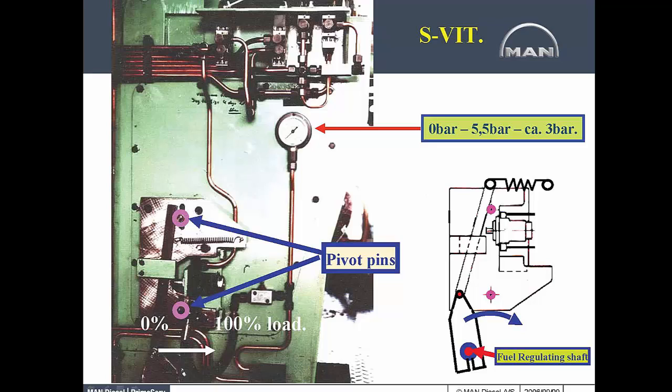And then you have 2 pins, these pivot pins. So if you look to your right, as that governor moves forward, that bar is going to pivot off the upper pin, and then it is going to start pushing at about 5 to 45% load on that air regulator, and it's going to change the air output going to the pneumatic actuator.